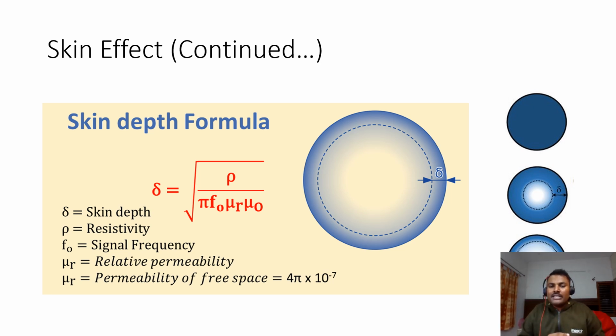This is why, when DC current flows, there is no frequency, so the whole cross sectional area is utilized for the current flow. But if AC current is passed, the depth is decided by this equation depending on the frequency. If a high frequency AC signal is passed, current flows only near the edge of the single-strip wire's cross section.